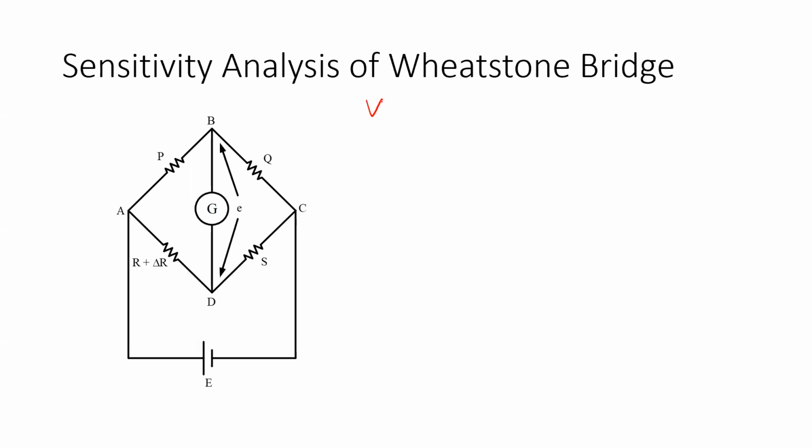So lower, why lower? Because then stability will be higher. But if it is lower, then you will not be able to check smaller changes. If you want to detect smaller changes, then with a device which has low sensitivity, you will not be able to check. So it should be as high as possible, so that a small change or small unbalance can be detected.